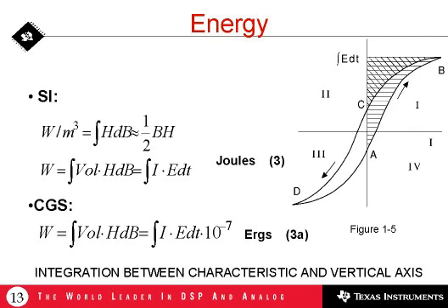And going from D to A, we're taking part of that energy back out. So from C to D to A, we have a symmetrical situation compared to A to B to C. So that's what happens to the energy transfer. We put quite a bit in, and we take only some of it out, and the rest is left behind as loss. Now, this core, as we're showing it here, would not make a very good inductor. It does have inductive capability, but what kind of an inductor is it that returns less than half of the energy that you're putting into it back to the circuit? Most of that energy is going into loss.